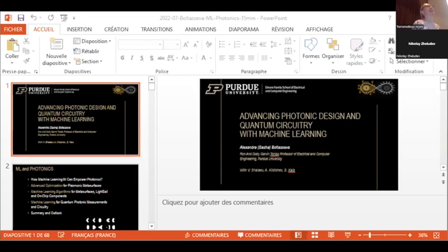But this is hybrid. Hybrid means that you will have to integrate dissimilar materials with dissimilar patterns and structures on a single chip and achieve high functionality. Just a single example that needs optimization and advanced approaches here would be the efficient design of an emitter, and the position of an emitter, in such a way that it effectively couples to the integrated waveguide. Not only the geometry of the cavity around an emitter needs optimization, but also there are many ways of architectures to be constructed.